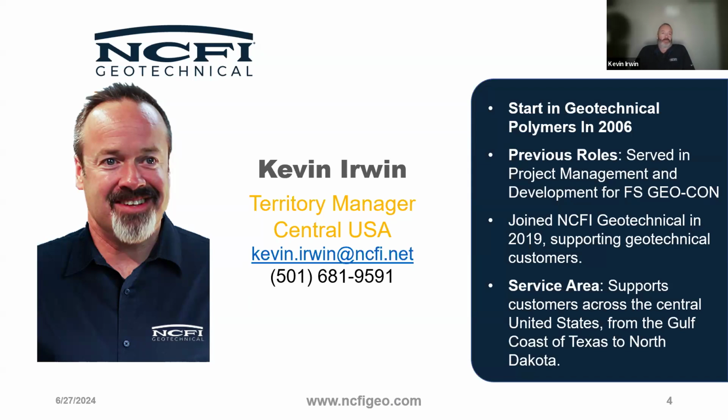We were trying to lift some stairs once. It was actually here in Hot Springs, as a matter of fact, and we had a problem because of the stem wall on the backside of the steps. That can be an issue, but that's because of the force that we're trying to lift. Just with foam in that case, I would probably look at some kind of a jack in addition to the foam. I can use a jack in that case, and then I don't think it's a deep injection issue though. In most cases, I wouldn't think, at least in my experience.